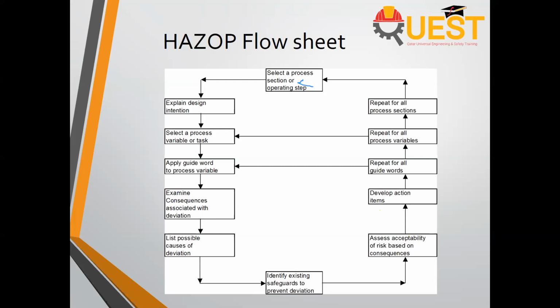For that, we have another session planned next week in which we'll give a brief idea of how to mark up a P&ID or a PFD prior to the HAZOP analysis, in which we'll mark based on nodes. Actually, we have nodes in HAZOP in which we have starting and ending points, and whatever happens in that node is considered as one section of HAZOP, a section of consideration.